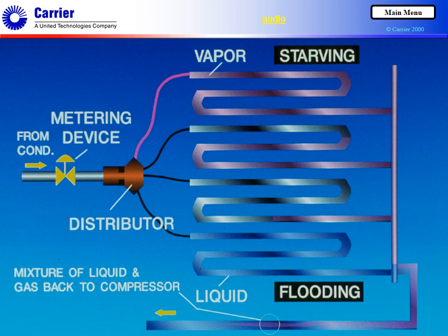An easy way to spot this malfunction is to check for higher temperatures at the tubes on the top circuits of the evaporator and lower temperatures at the bottom tubes. The solution for this problem is to replace the nozzle with the next smaller size, or to rearrange the controls to shut off one section of the evaporator before the low limit is exceeded.